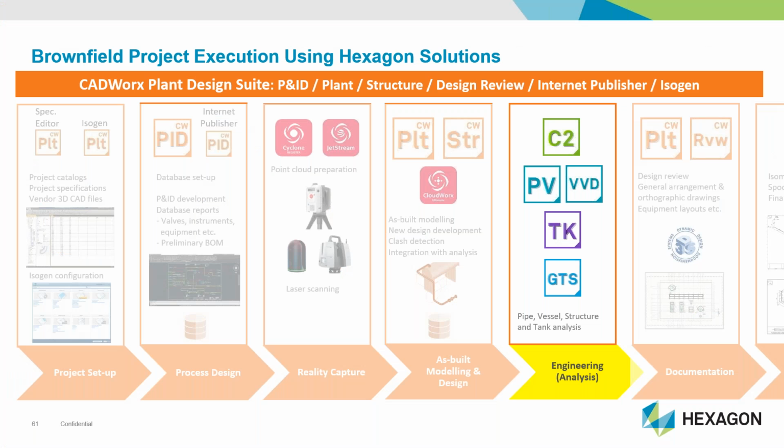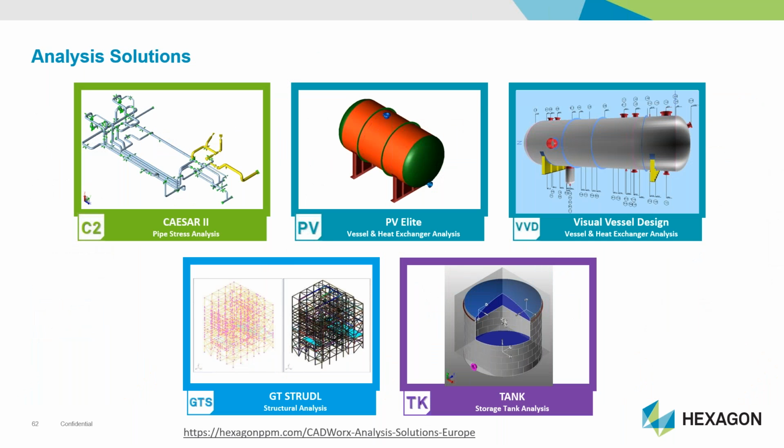So with the design finished, the next step is to perform engineering analysis to ensure the designed items, piping, equipment and structure are safe and code compliant. Whether existing piping is being replaced or new pipework is being installed, if it's part of or will tie into a high pressure, high temperature system, to ensure a safe design is produced, piping usually needs to be stress analysed.